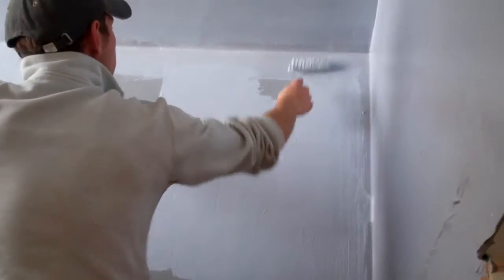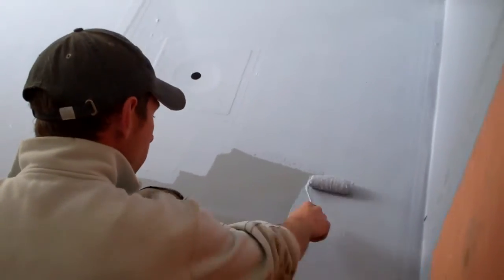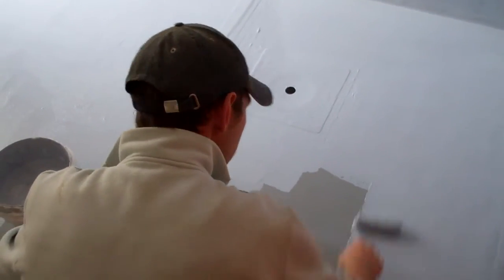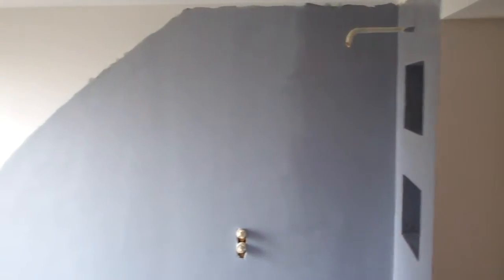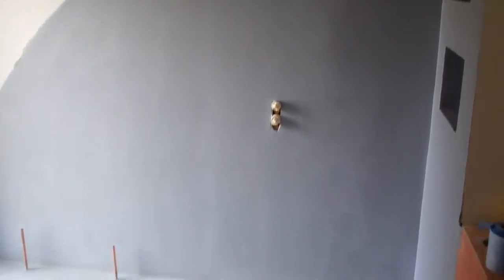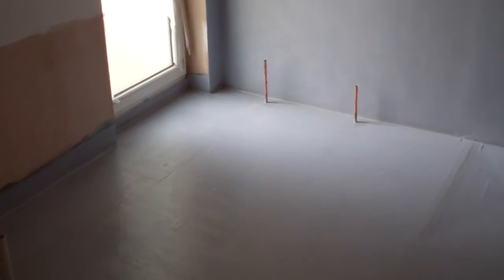The time between coats of aquaproof compound will vary depending on temperature and humidity, but will normally be at least 4 hours. It is easy to see when the aquaproof is ready for overcoating, as it dries to a darker shade of grey. This is very useful when applying the second coat, as it's easy to see if you have missed anywhere. We now have a fully tanked wet room with a slope to falls in the immediate shower area.